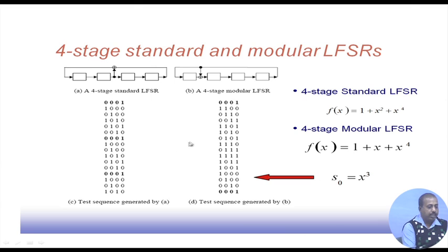On the other hand, if you look at this particular LFSR, you start with 0001 and follow the logic that is captured by this, giving clock signals to the flip flops continually. After initializing with 0001, this 1 is coming back to the first cell, and the second cell gets the sum of the last cell and the first cell.